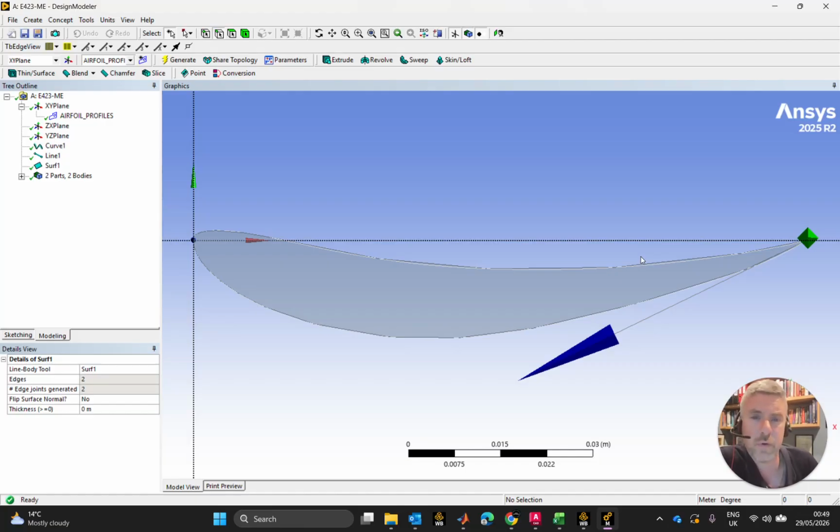Now I can make it 400 if I want. I can make it 300 mil, but I want to be able to generate a certain amount of downforce on this, right? So I want to be able to show the judges and the scrutineers that this is the sort of downforce that this wing can, by simulation study, achieve. That is important because if you enter the competition in around end of December, January, you need to send in a design concept specification, and on that, you may be asked, or you may have put in, what your target downforce is going to be.